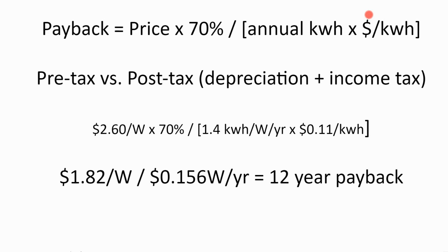If you don't have net metering, a good way to do it is take 2/3 of your outflow rate and 1/3 of your inflow rate to get your effective generation rate. Take your PV Watts number, your effective generation rate, and your price divided by your production value will give you your simple payback.